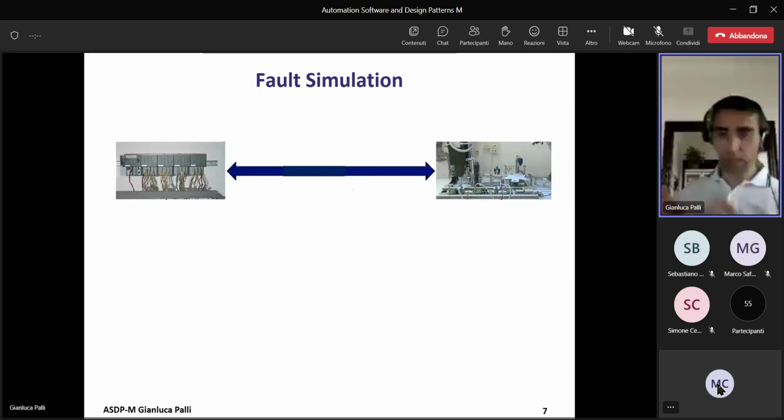For the design of the finite state machine, you have to consider all the steps, but they are not so complex. You have many, but it's not so complex. Of course, how to organize this in the best way is one of the main topics in the design of finite state machines. This is a suggestion: you have 4 stations, so I suppose a good organization is probably to have one finite state machine for each station and a finite state machine managing how the different stations are connected one to the other.